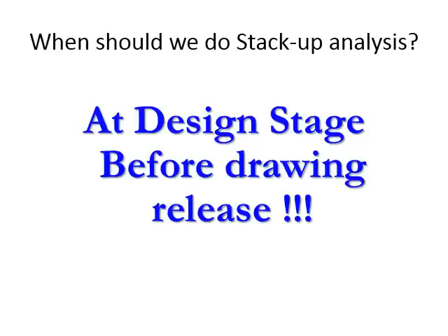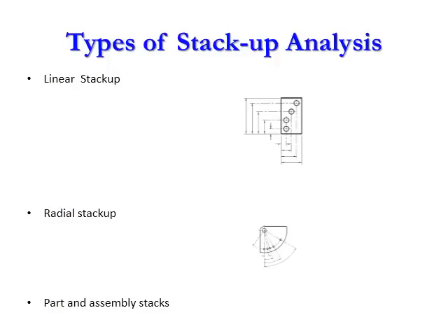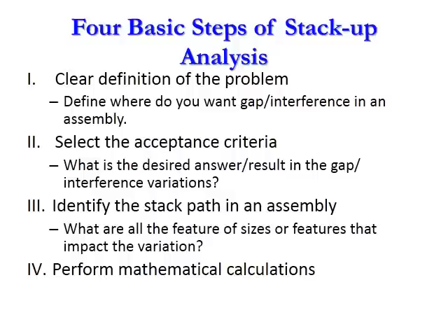When should we do stackup analysis? At design stage before drawing release. Types of stackup analysis: a linear stackup, a radial stackup, part and assembly stackups. Four basic steps of stackup analysis.